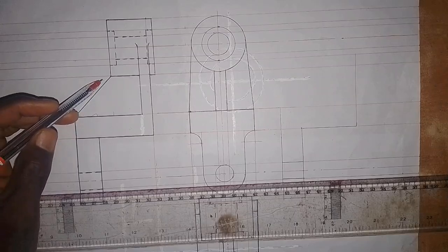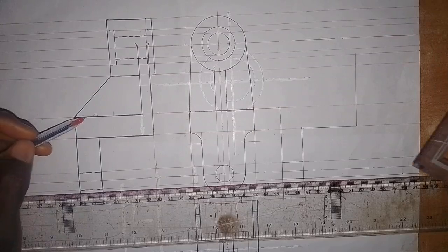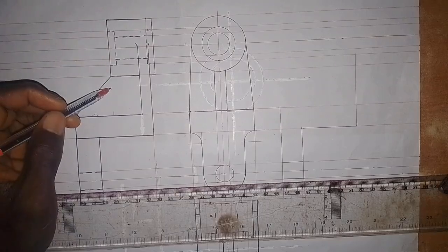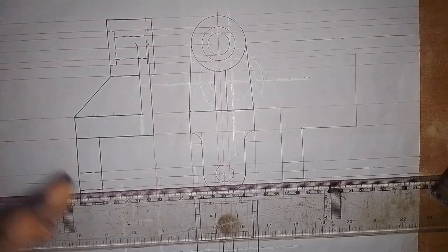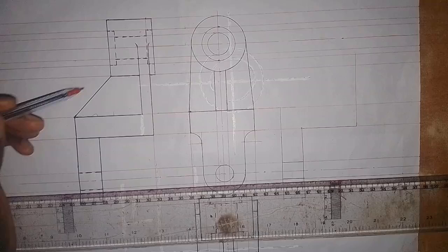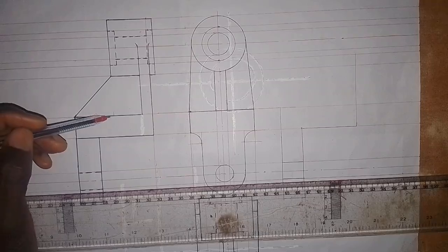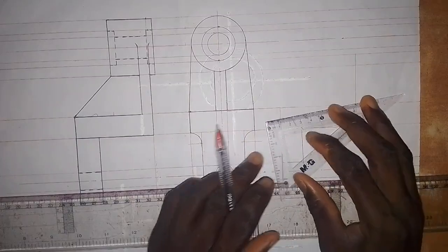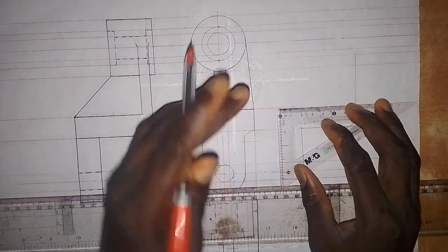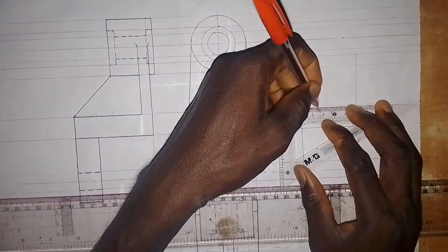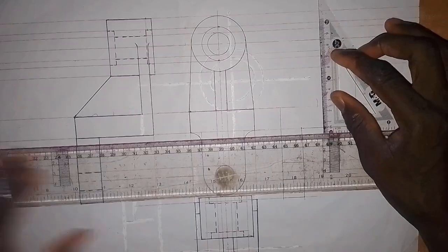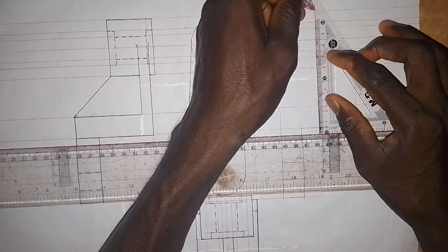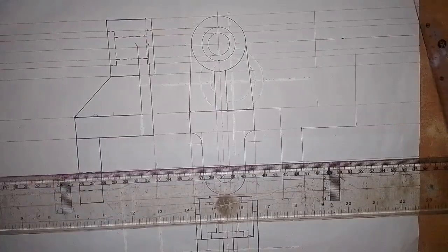Now, for us to locate this surface, this line, on this cylindrical part, as we have in the drawing which I've shown before, we have to take a measurement of 35 millimeters from this point backward here, so that we can draw this line. As we did where we made the orthographic views of the object, we take a measurement of 35 millimeters from here backward. Then we come up here and we draw a vertical line from here up. So we have it for the cylindrical part that we have here.